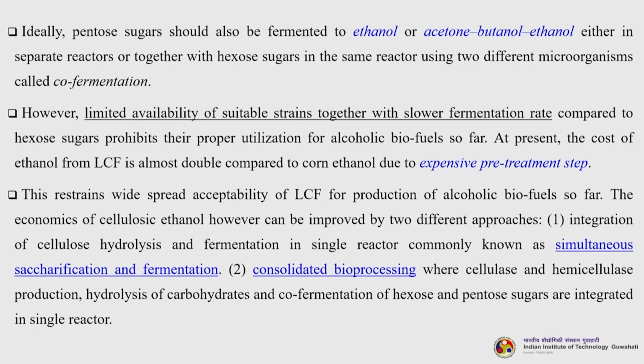However, limited availability of suitable strains together with slower fermentation rate compared to hexose sugars prohibits their proper utilization for alcoholic biofuels so far. At present, the cost of ethanol from the LCF is almost double compared to that of the corn ethanol due to the expensive pretreatment step. Now, this restrains widespread acceptability of the lignocellulosic feedstock for production of alcoholic biofuels so far.